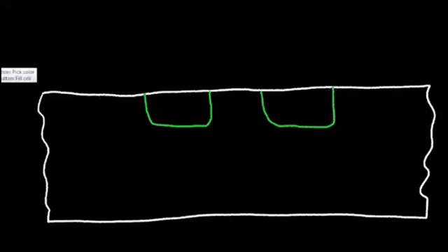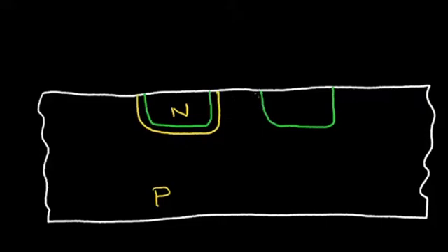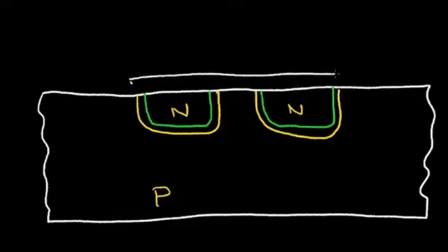And I know that between this P material and this N material, I'm going to have a depletion region. It'll look something like this. And this N region over here will have a similar depletion region. Now, if I grow a glass region, let's say I grow a layer of glass on top of this structure, and I add over here a conducting electrode.